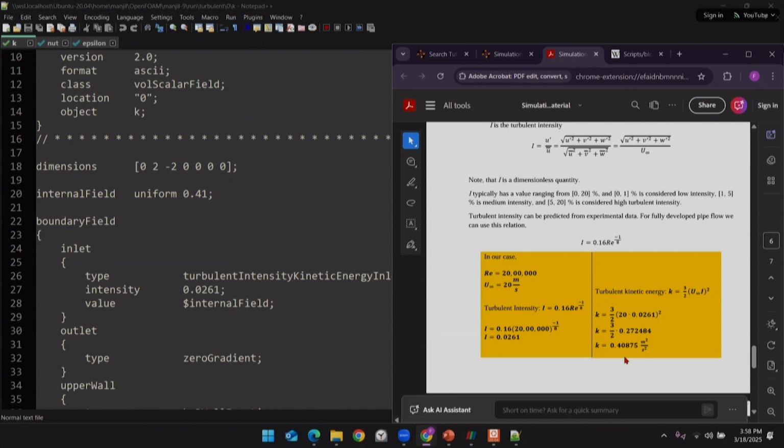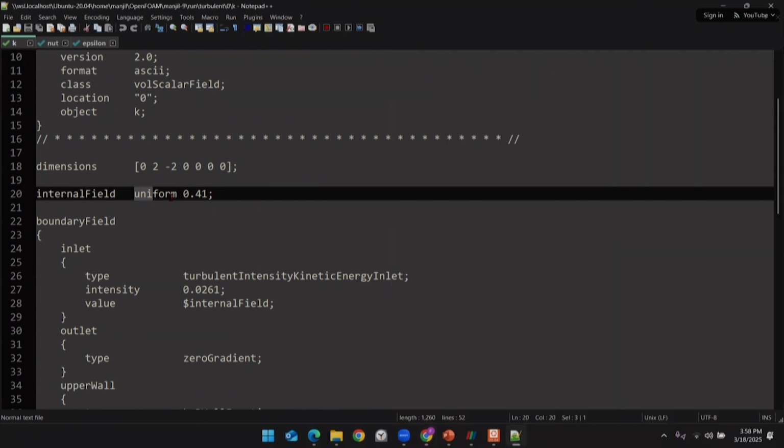This is the initial value that we want to initialize our solution with. You cannot choose an arbitrary value, because this will lead to inaccurate solutions and also might lead to divergence. So it is always advisable to calculate it properly. Also, the k-omega model is very sensitive to these free stream or initial values, so this calculation should be very proper.